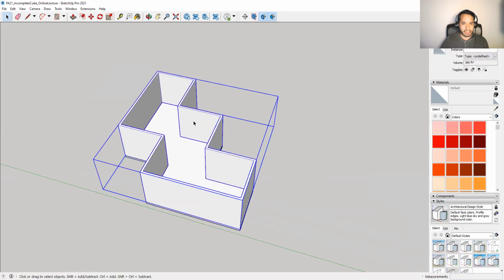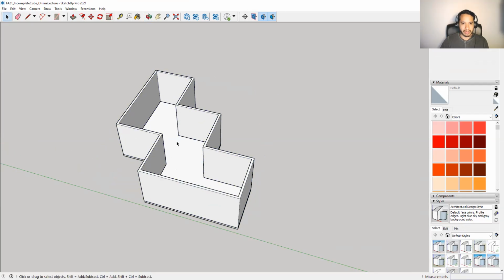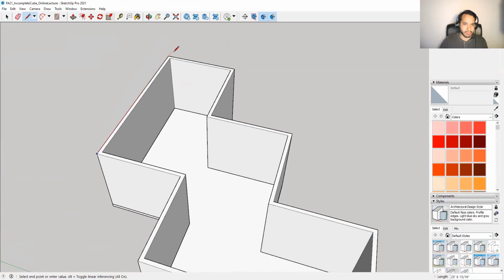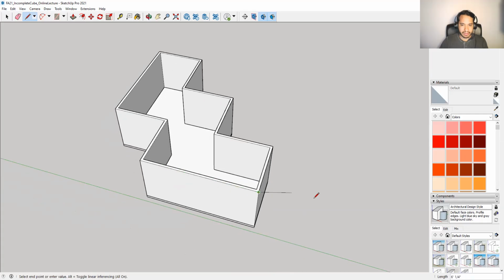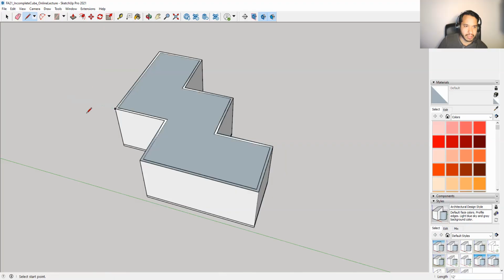So now we have floors and we have walls. Now I'm going to create the ceiling, and I'll create the ceiling the same exact way. I'm going to use the line tool. Again, notice how the line is attached to the pencil after every single click, right after I click on every single corner. If that's not happening to you, then that means that you have some overlapping geometry, some overlapping lines. Now notice what happens when I finish the loop. The line is no longer attached to the pencil.